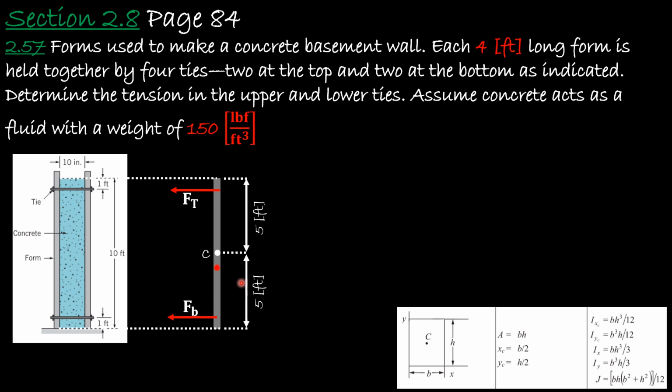All right. And the force, which is the hydrostatic force on a plane surface in here, will act at the center of pressure, which is usually a little bit below the centroid. So that will be the resultant net force. And this will be the location of the resultant net force from the liquid surface. And here we will take the moment at the bottom. You can take also the moment at the top.